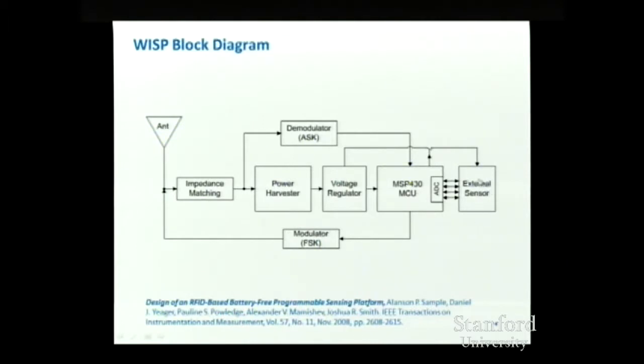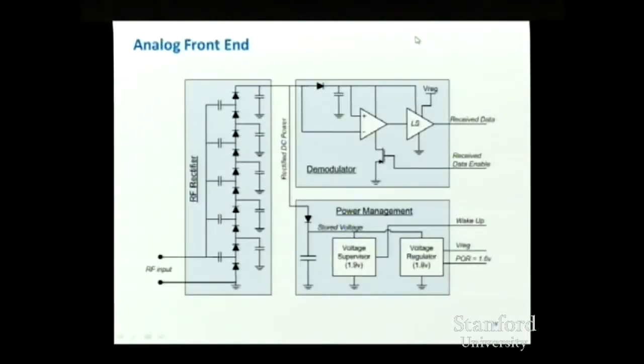So these blocks over here on the right are the pieces that are unique to the WISP. There's a microcontroller with ADC and then external sensors. And the state machine, instead of being implemented in discrete dedicated logic, is actually software. And that means we can program it, which has a lot of exciting possibilities.